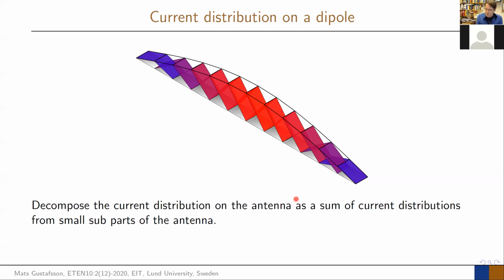So instead of saying that this is a dipole, which is very long, we say let's treat the radiation from this piece separately, the radiation from the current that sits here separately, there separately, and then I want the field, so I just take the sum of all of those. We can sum up all of those contributions from the different pieces, and then I get the total field. That's how we're going to determine what is radiated.